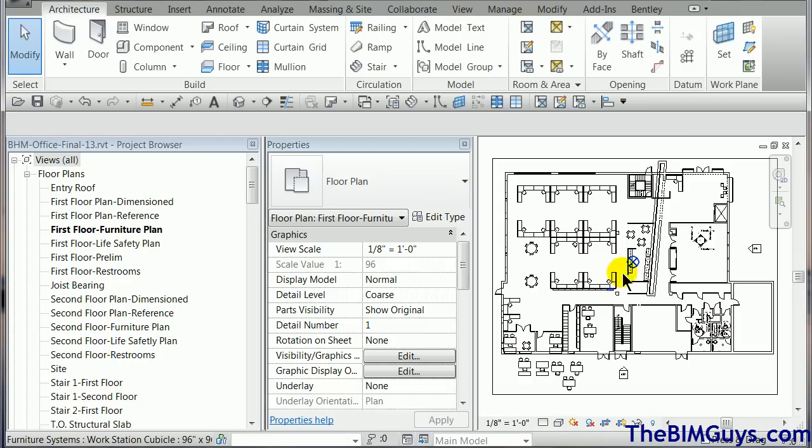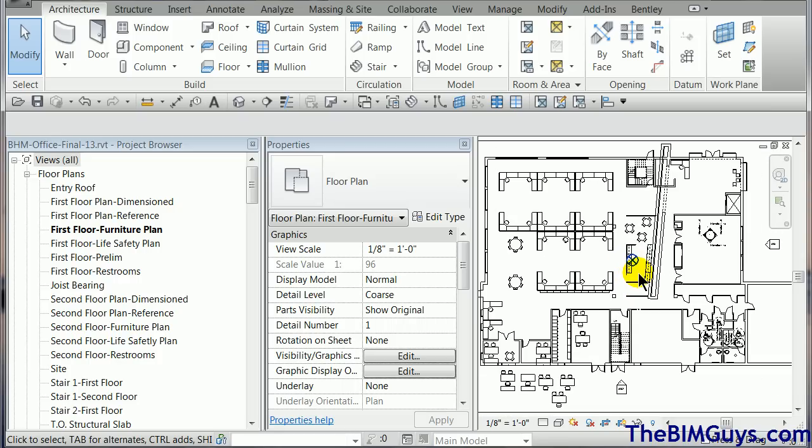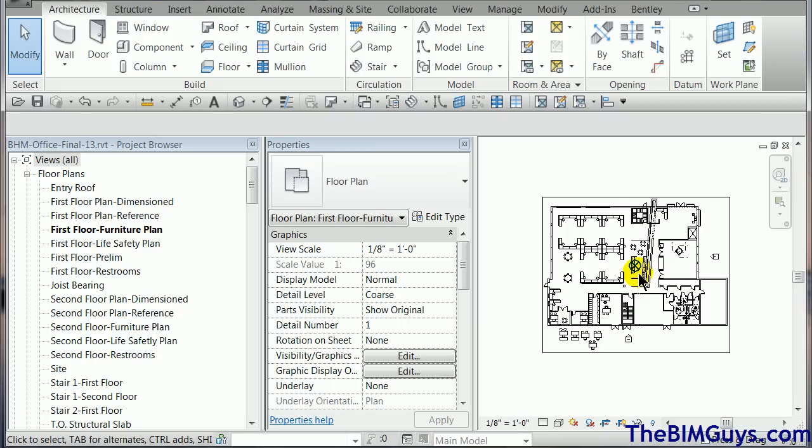You notice that the project point is that little circle. This is the one that you're going to relate to your building, and this is the one that the levels tie into by default. Okay. Now this little guy here, if I want to see where it is or see more about it, there it is. Now it's going to grow or get smaller as I move about. Now with this, one of the golden rules of Revit is never move your building, because there are so many things associated with it that if you move the building, everything's going to blow up. What we're going to do is we're actually going to move the 0, 0. We're going to move the 0, 0 to the actual corner of the building.